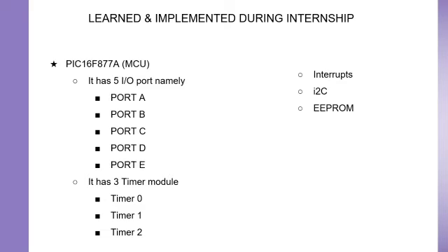Working of the I2C communication protocol. It uses only two bidirectional open drain lines for data communication, called SDA and SCL. Both these lines are pulled high. Serial data, SDA: transfer of data takes place through this pin. Serial clock, SCL: it carries the clock signal. I2C operates in two modes: the first is master mode and the second is slave mode. Each data bit transferred on the SDA line is synchronized by the high to low pulse of each clock on the SCL line.